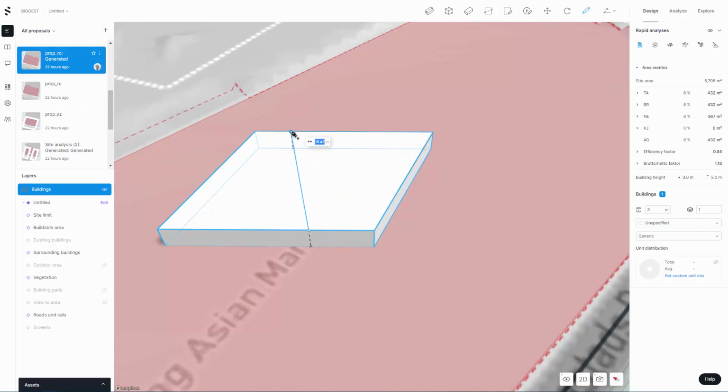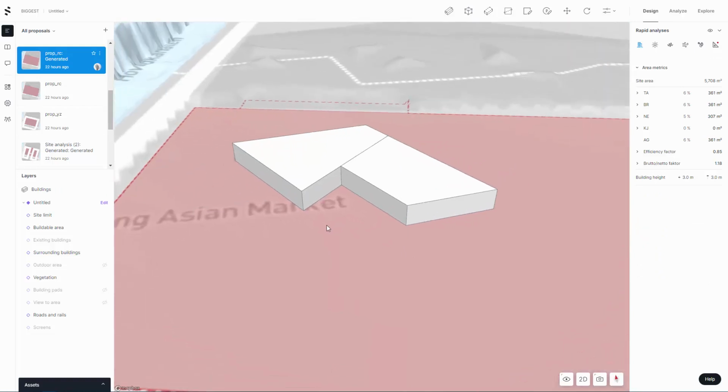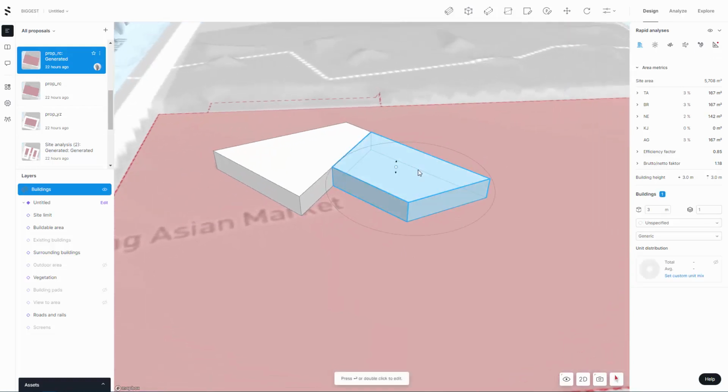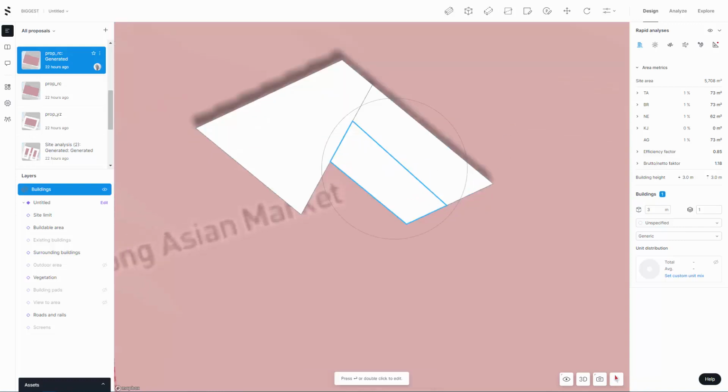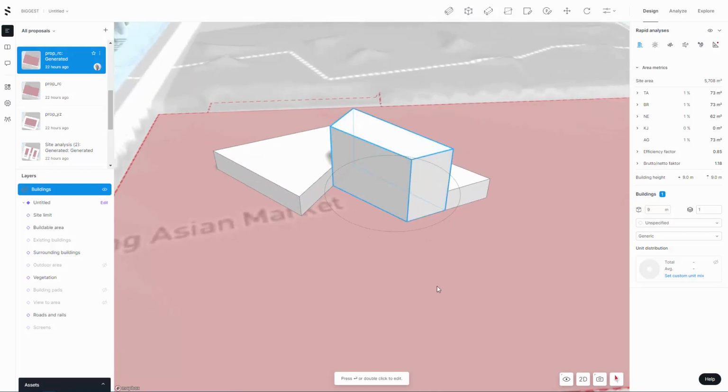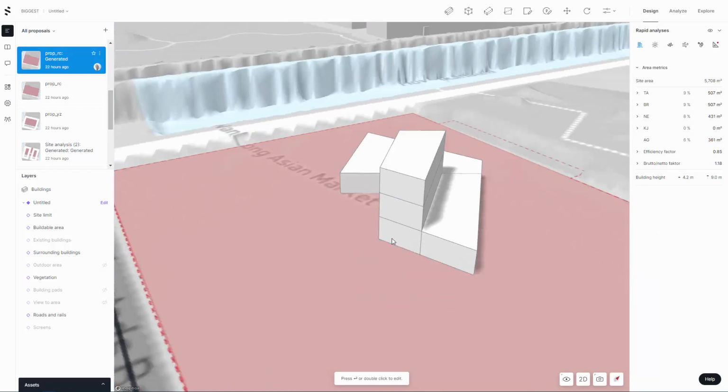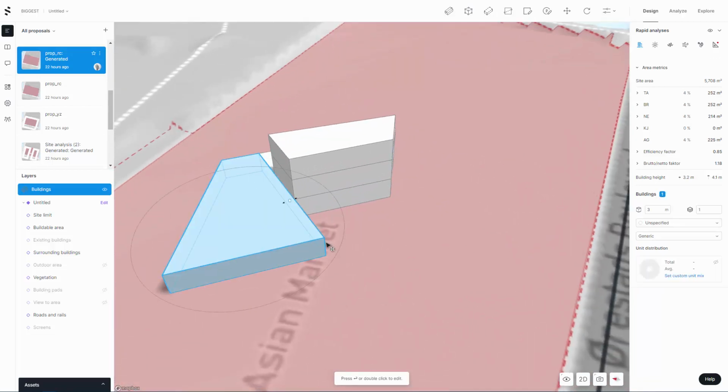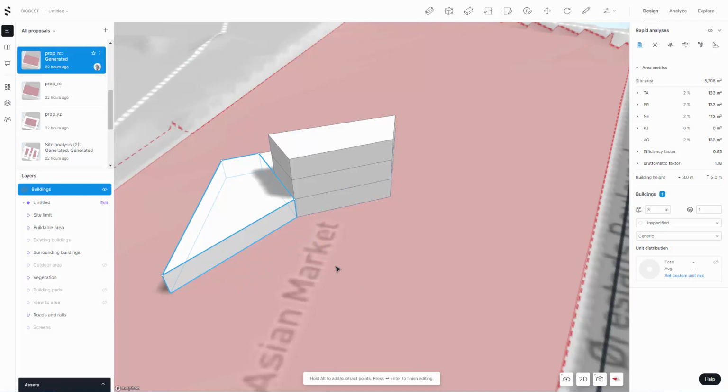There's a nice little feature here that will break it, and then we can use this tool to reduce that back a little bit. A handy tool should you want to get into more detail and draw walls across your building. What I could do now is crank that up to 9, go to 3D, and another thing you can do is split into stories as well. Really simple, easy to use point and shoot tool, and you can see the snaps work great there.